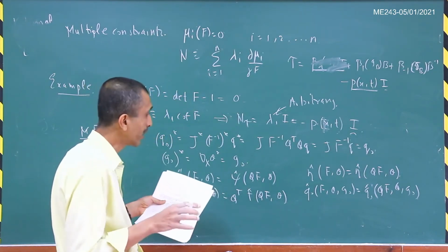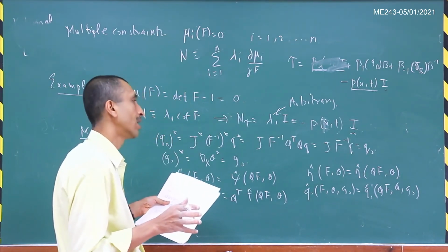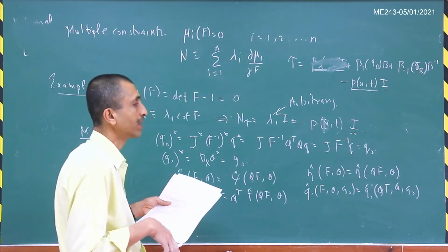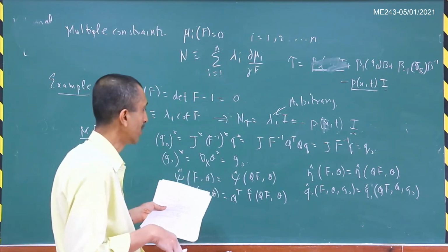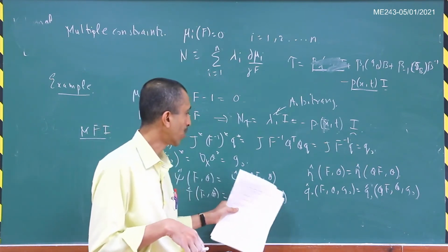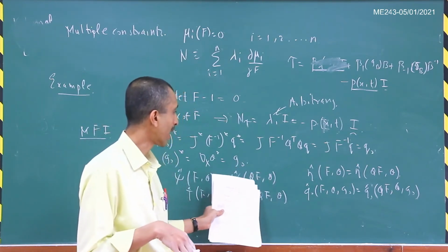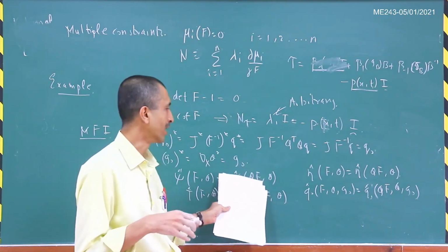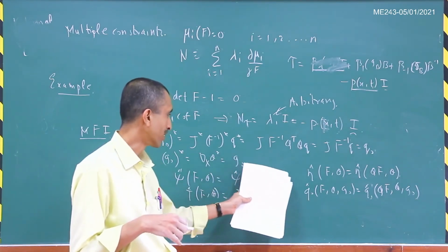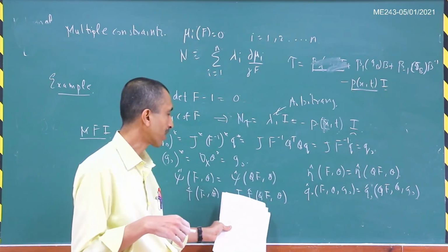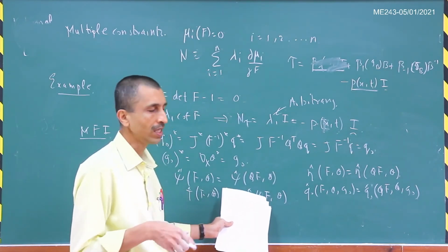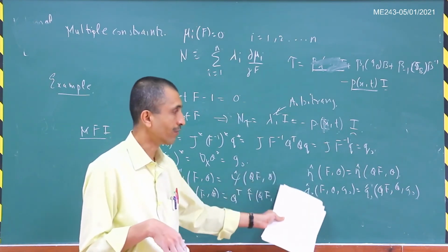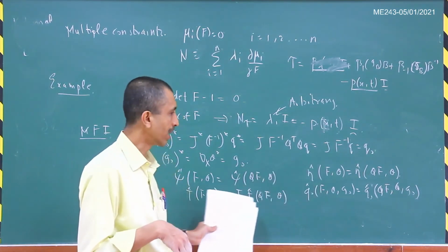So we have already incorporated the restrictions imposed by the second law of thermodynamics. For example, we are now no longer assuming that psi depends on G naught. We have already shown that the free energy, the entropy function, and the first Piola-Kirchhoff stress cannot depend on the temperature gradient, and that conclusion we have already incorporated in these constitutive relations.